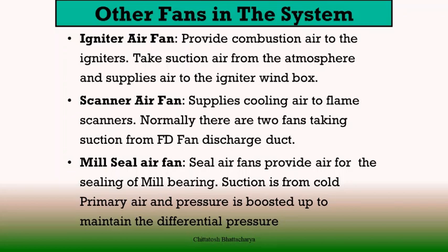Then we have scanner air fans. Scanner air fans are installed to cool the flame scanners, which cannot operate at a temperature beyond 90 degrees centigrade. They are open to radiation heat within the furnace. So naturally we need continuous cooling of these flame scanners through scanner air fans. We have both AC and DC scanner air fans.